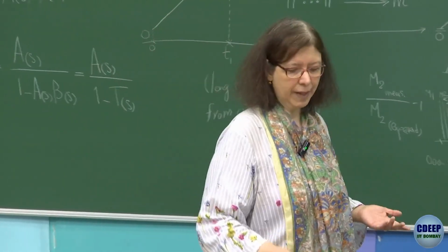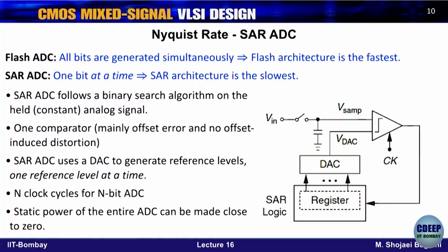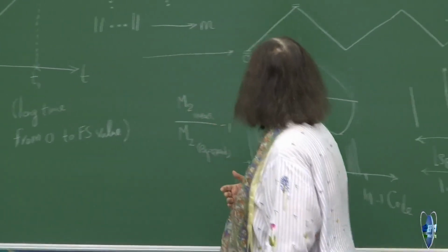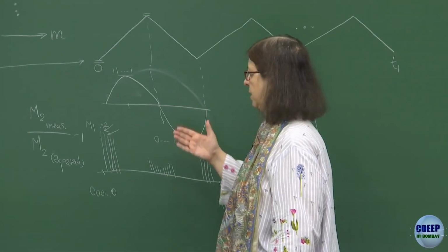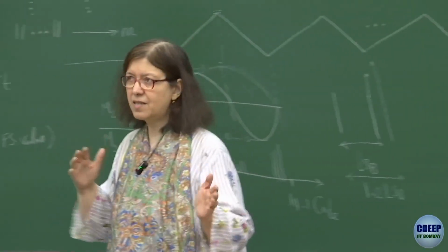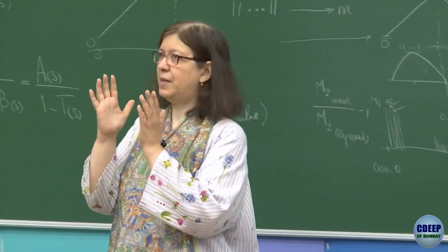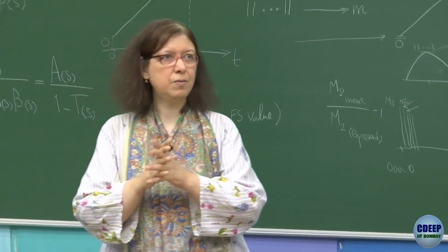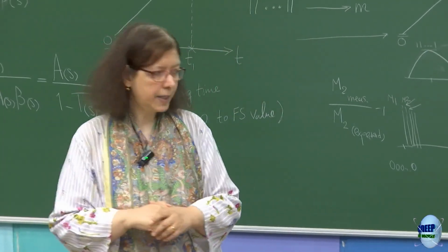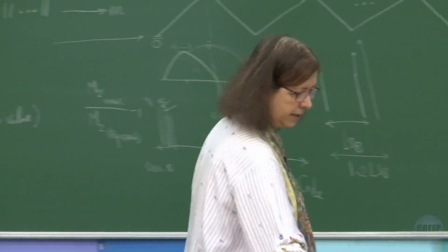With the binary search algorithm, first it divides the code into two parts, and then we see whether the input is below or above the middle value of the codes. So eventually, it divides the full scale into half.